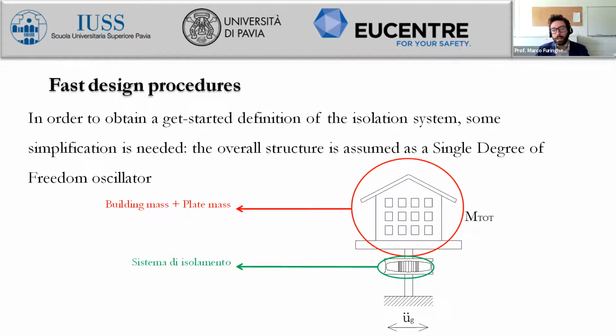We will be comparing the displacement time signals at the isolation system returned by the nonlinear time history analysis performed on the full 3D finite element model. And we will compare these to the outcomes of the time integration of a single degree of freedom oscillator. We will learn how to model a single degree of freedom oscillator in a non-linear way.